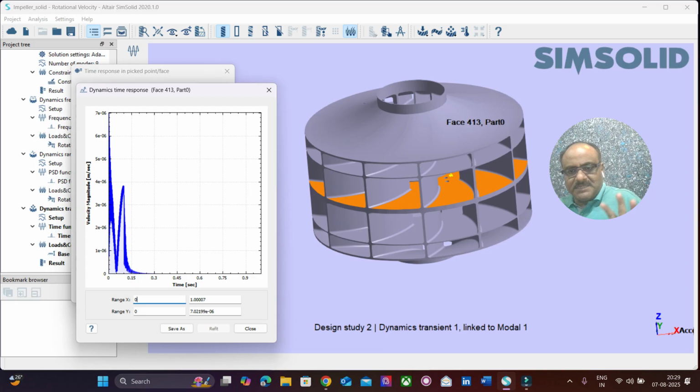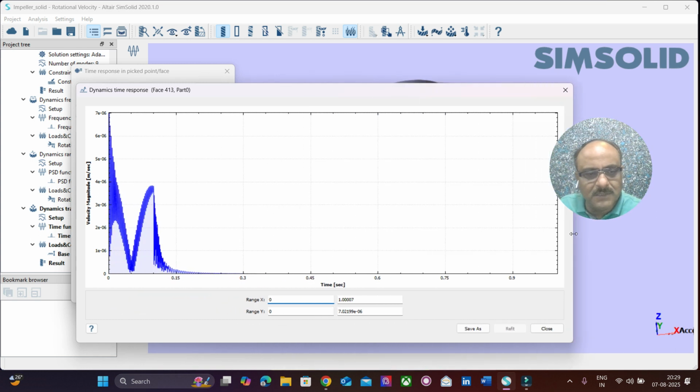These base excitation kind of simulations are even performed in structural engineering, in most structures, the building structures, the cooling towers, for any bridge structures, for all kinds of structures. A seismic analysis or earthquake analysis is performed exactly this way. This is called the direct transient formulation or method with which we are finding the spectrum. Here we will find the velocity spectrum. So this is how the velocity is going to be.